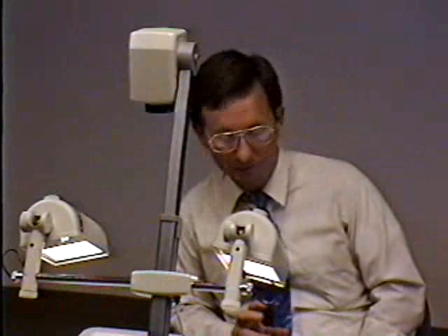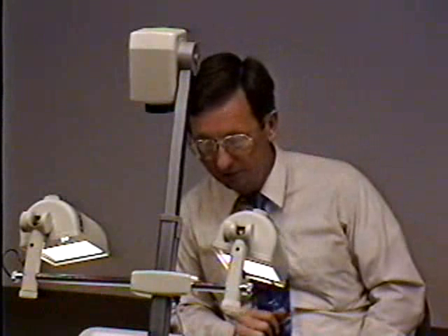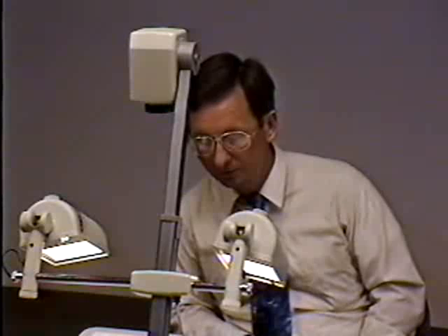So again, I've just taken the data, and used the data, reduced it down to 2 parameters, a mean and a standard deviation, and then used my probability distribution function, a probabilistic model of the peak annual flows, to assign an exceedance probability or a recurrence interval to any given flow.